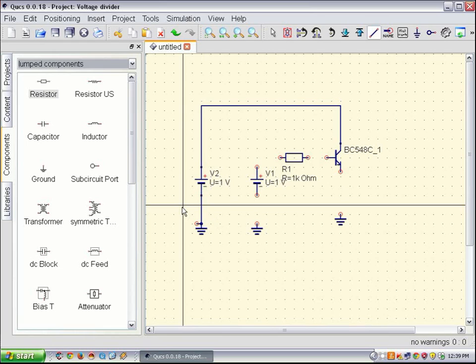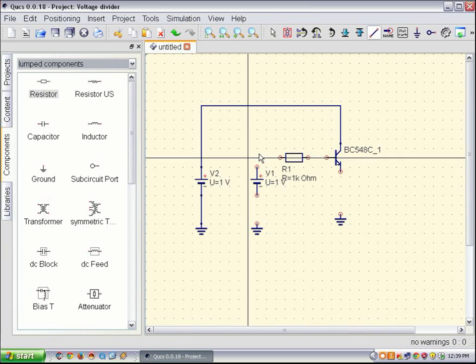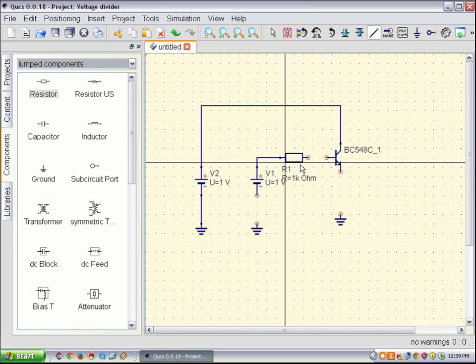So that's the extra wire here. So I'll just delete this by using the delete key on the keyboard. I'll just click on the wire and it will go. Now I'll come back to Control E and continue my wiring.